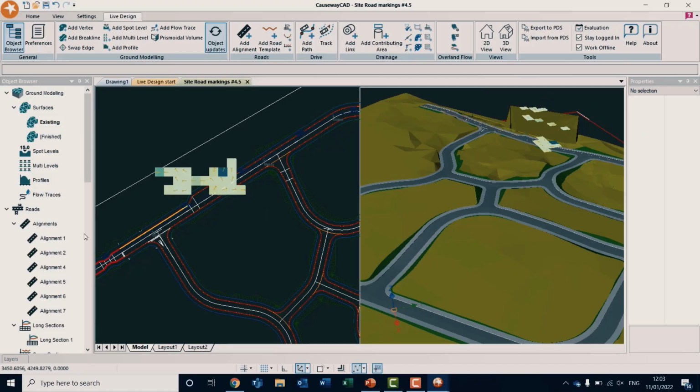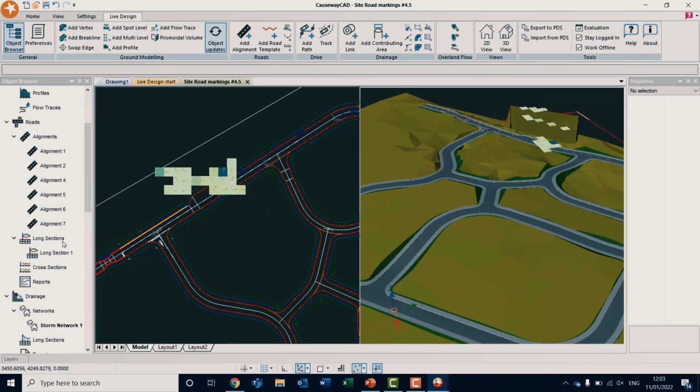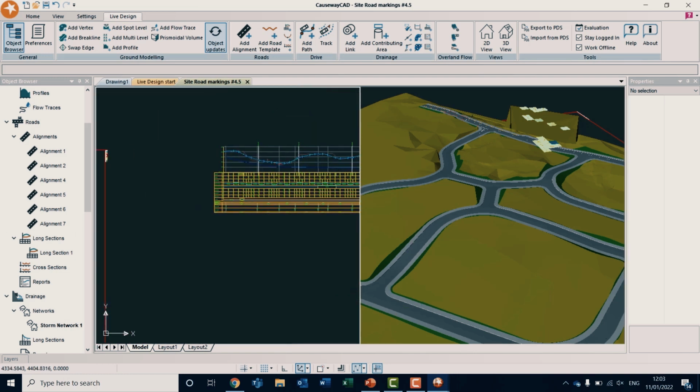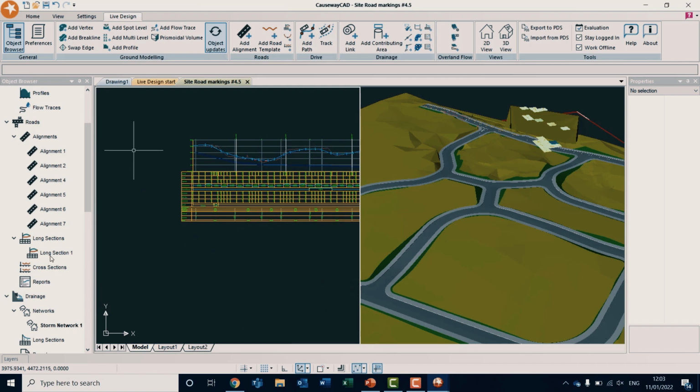And then you design your roads, and you have so many styles and settings for the roads that the possibilities depend on what you want. And then you put your drainage. If the drainage doesn't work, you change the road to suit the drainage, and you don't have to go back and forth. You're in the same software. And then you edit it in Flow. You add your storage, make sure it works, bring it back to the Overland Analysis.